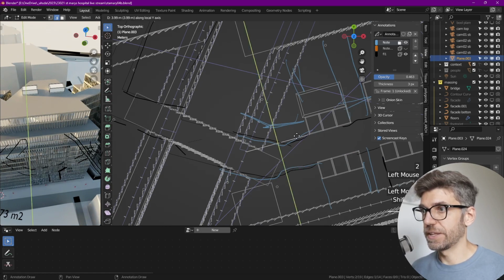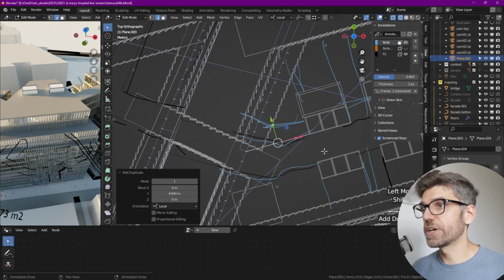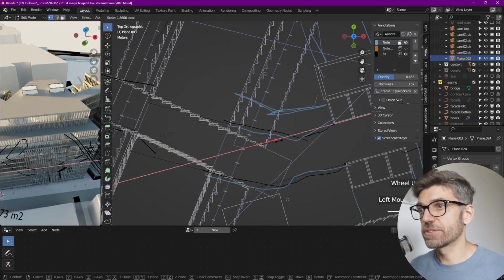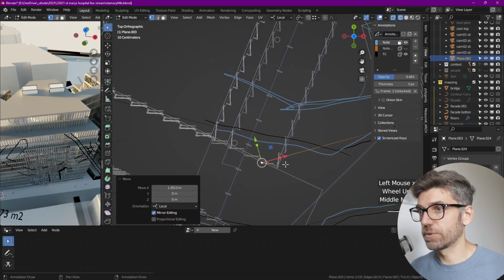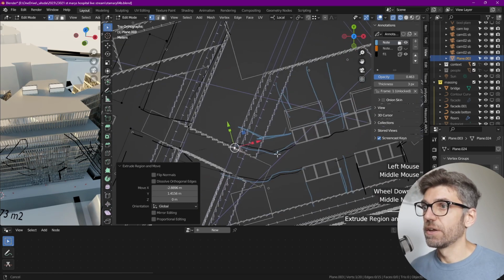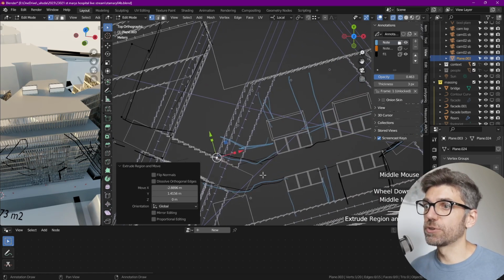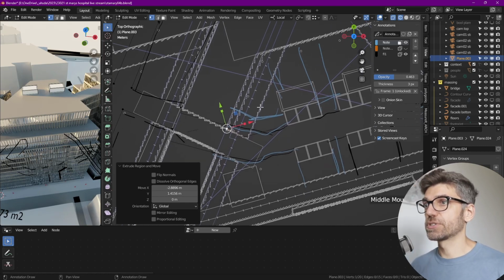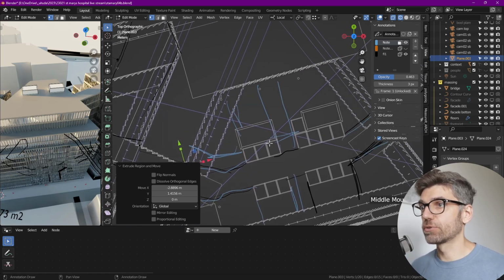Let's duplicate that edge over here. That's more generous here than it needs to be because that's the waiting area. So we don't need to be as generous once we get closer to the corridor, because only half the people are going to go in that direction, even less than half, right? So then we go over here and we have to think now. We should have doors that enter in there, and that depth, you know, that's a suite depth. So we don't need to worry about any more internal corridors over here.